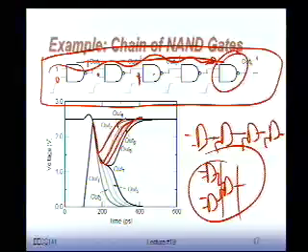So what they often do actually in logic synthesis, which is kind of interesting, if you take Synopsys and you feed it through the synthesis path, if they see a very long unbalanced path, they actually might inject inverters in there just to balance the paths out a little bit more. That's something that some of those logic synthesis tools do to remove basically glitching effects. Okay?